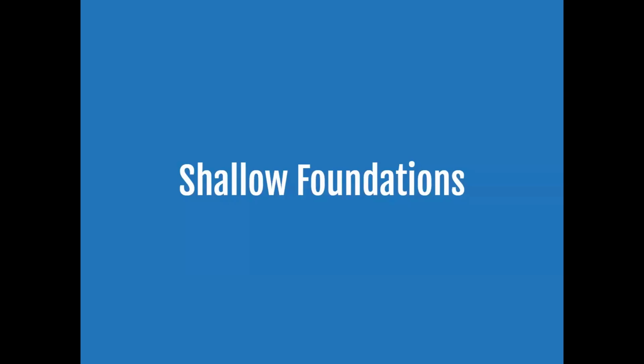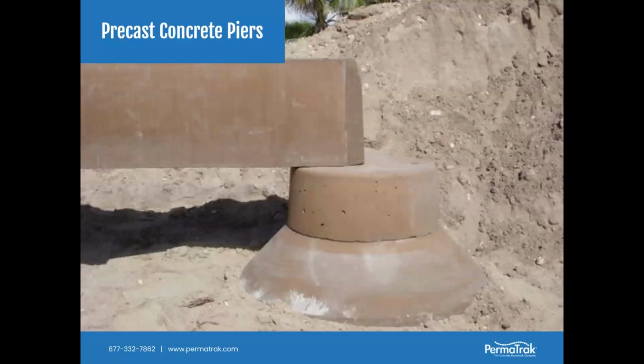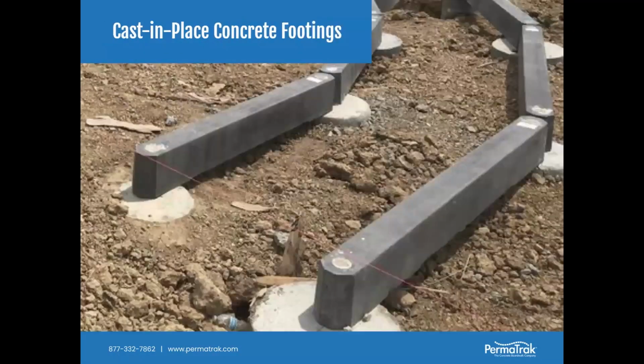I'll start with shallow foundations. So here's the shallow foundation option, probably your least cost effective, not going to be very applicable to maybe a wetland environment per se, but on boardwalks where you have upland soils, a precast footing could work just fine. These would be a stackable component system. The top component in the middle of the screen could be repeated 2, 3, 4 times on top of each other to extend the height of the pier. So this is just a stackable precast foundation system.